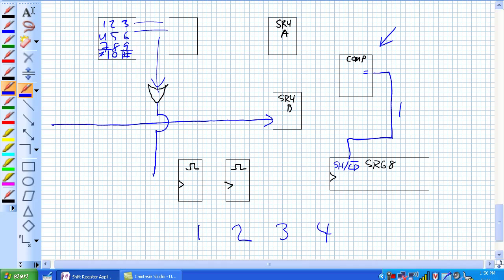So that is a positive edge transition. It's telling that one shot, okay, let's go ahead. And in this particular example, it's using a negative edge being fed to that one. And from there, that was our load command, so load the first digit. This clock right there is getting that low, then it comes back up.